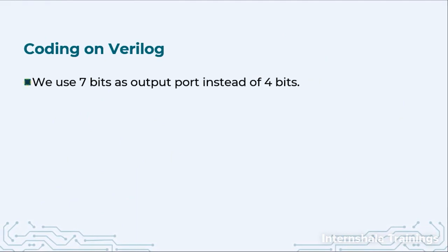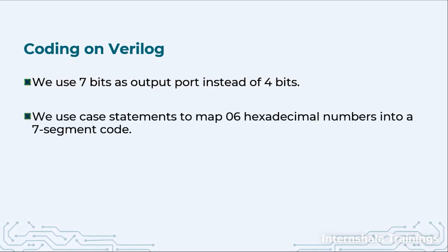Now, how do we code it? That is also an interesting question. We are going to use 7 bits as our output, not the 4 bits as our sum, because now we want to control 7 different LEDs. We will use a case statement.